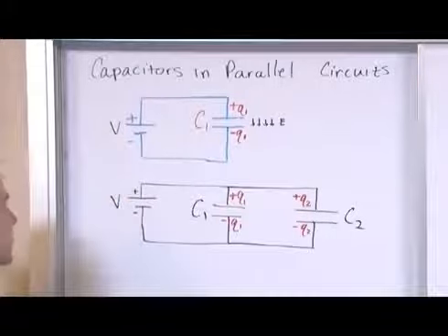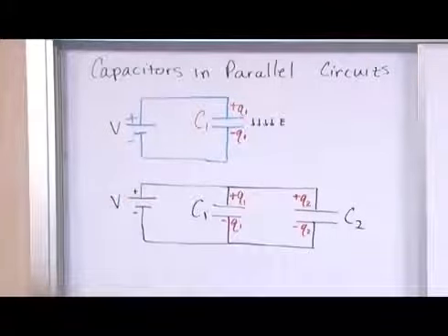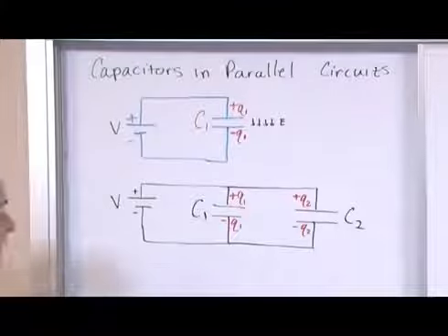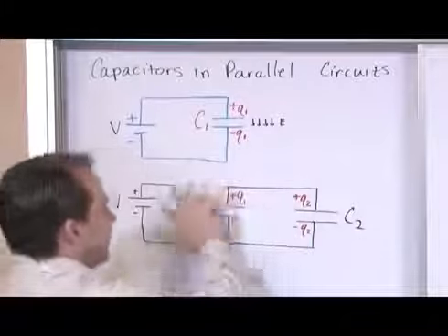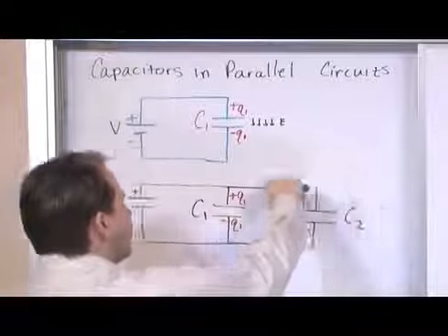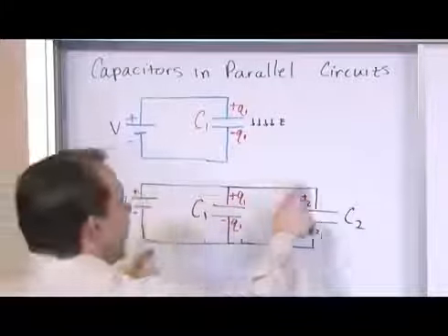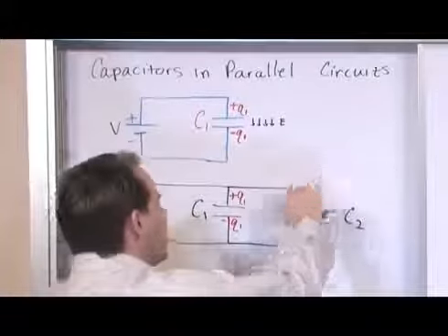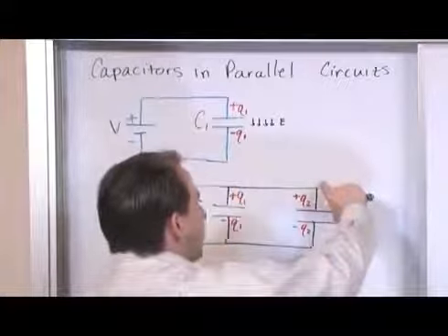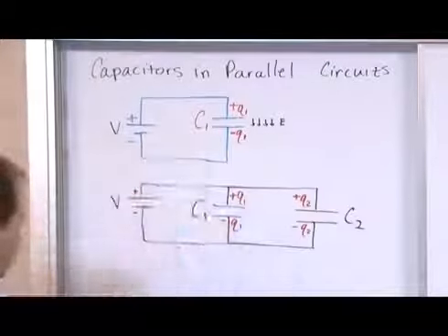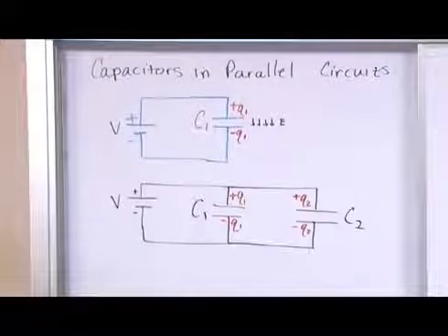That's one thing you have to look at when you're thinking about circuits and really start to understand it. It only comes with practice. You have to think about this a little bit. Pretend this capacitor isn't even here at all. This capacitor really is connected directly to the battery because these are wires that go all the way to the other capacitor. So from this point of view, this capacitor really isn't even here. This guy is connected directly to the voltage source, which is right here.